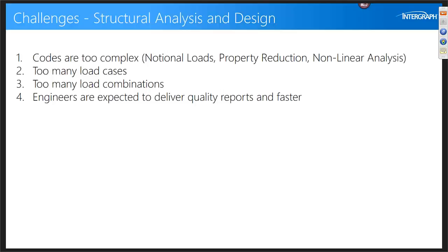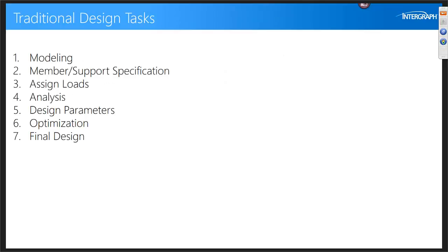Okay, but at the end, what we think is the engineer working on this project basically loses a sense of what's a governing load case. Have I really selected the sizes to begin with to perform a full-fledged nonlinear analysis? Is it really going to work with even the dead load applied or the self-weight applied? So those types of calls need to be made before you jump on to complex analysis, and I'm going to show you the whole process and how this can easily allow you to get to the solution without spending time reviewing results for 700 load combinations at the beginning.